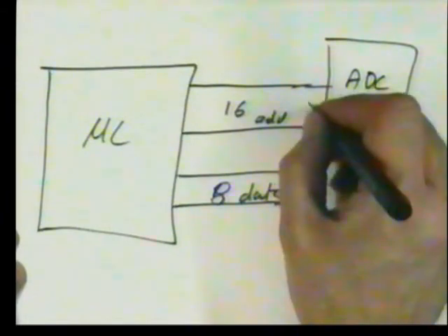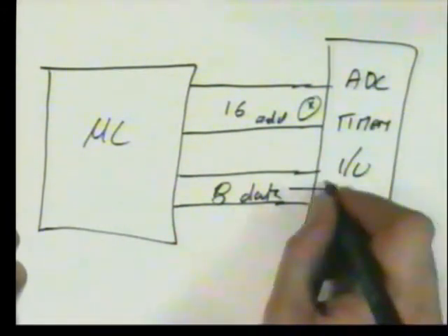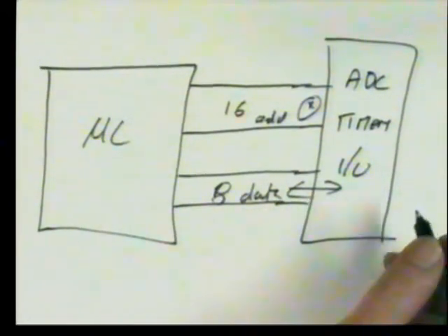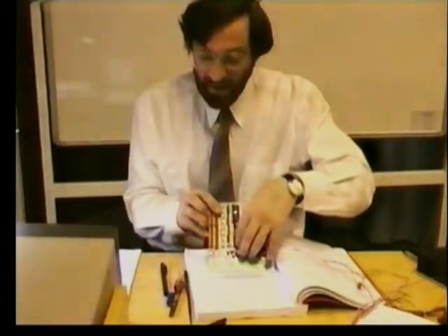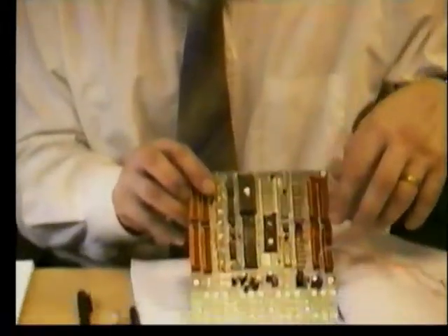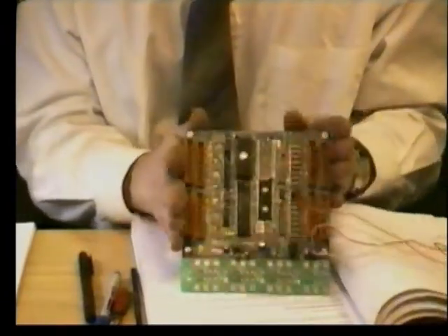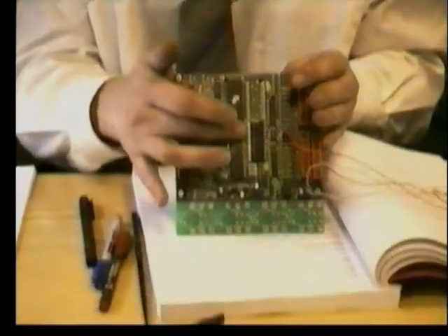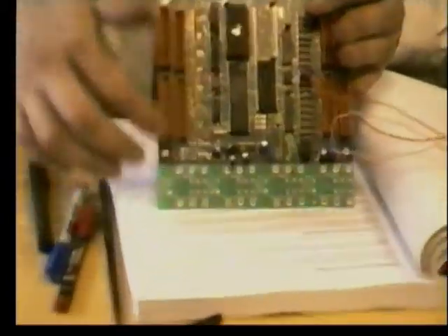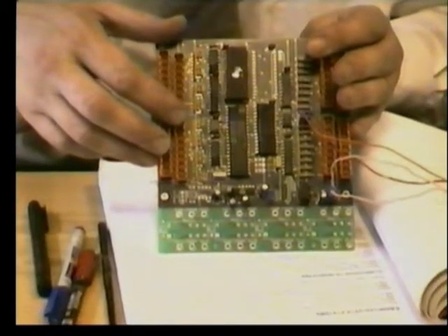Each device is given a unique address in the memory map, and then it communicates backwards and forwards via the 8-bit data bus. That is the standard traditional computer structure. Bus orientated. The problem with bus orientated systems is you end up with enormous processor cards like this. So even though we might have started with a nice compact microcomputer in the middle, we've had to expand it all out into a far larger system, a far larger board. There's the microcontroller. Everything we had hoped we would need is on there, but we've had to expand it all out onto a far larger board.